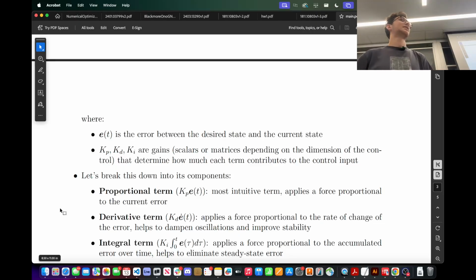Another thing is, say I have my static friction example here, and I have an integral term, and I'm pushing this thing, I overcome static friction, and I get to where the eraser was. And then I change my set point. So I'm here and I'm good for a second, and then I change the set point. Now all of a sudden, you have all of this error built up from your previous set point, and that can throw you off in very weird ways. And so if you're not careful about resetting the integral term or putting limits on how big it can get,